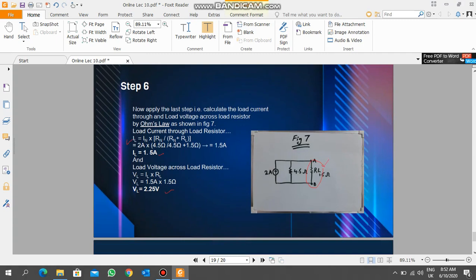So this is our 3 ohm resistor, this resistor. You remember last time when we found the current, we took this resistor and this. So now we are calculating and measuring the open circuit resistance. This is the Norton. We have reduced the 12 V DC source to 0, and the equivalent is replaced with a short circuit as shown in figure 4.